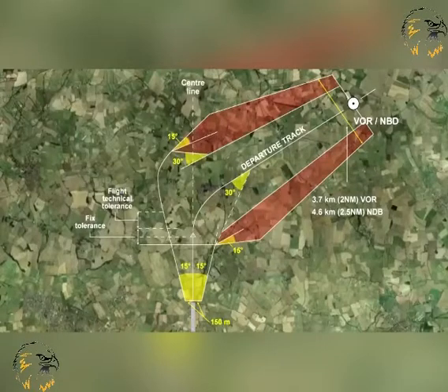If a departure requires a turn of more than 15 degrees, a turning area is constructed, and the turn required is to be commenced upon reaching a specified altitude or height at a fixed facility, like a VOR or NDB. Straight flight is assumed until reaching an altitude of at least 394 feet above the elevation of the DER. At least 90 meters of obstruction clearance must be guaranteed in the turning area.